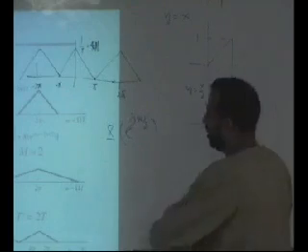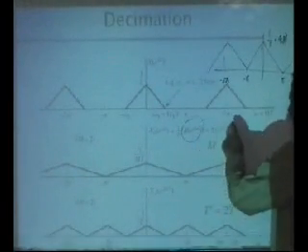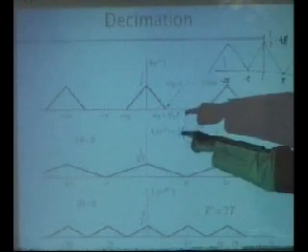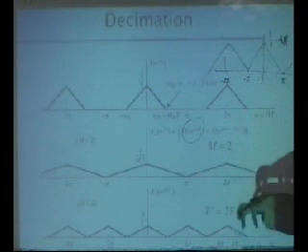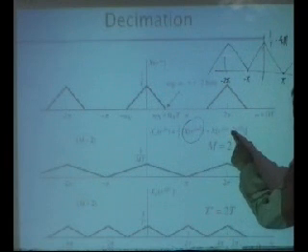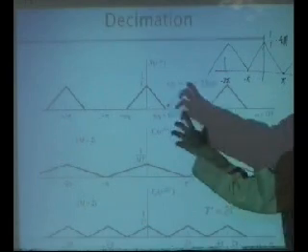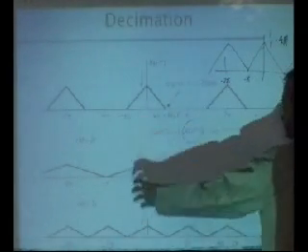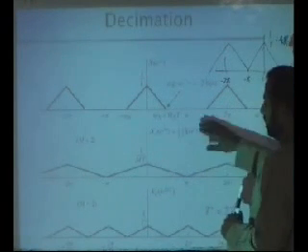So mathematically you write X of e to the j omega over 2. But this will take 2 pi to 4 pi and minus 2 pi to minus 4 pi. So you have another copy which comes at 2 pi and minus 2 pi. This is X of e to the j (omega minus 2 pi) over 2. So this is an extra copy of the spectrum everywhere, which will come at 2 pi and minus 2 pi and 6 pi and minus 6 pi. And there is a mathematical proof of this expression.